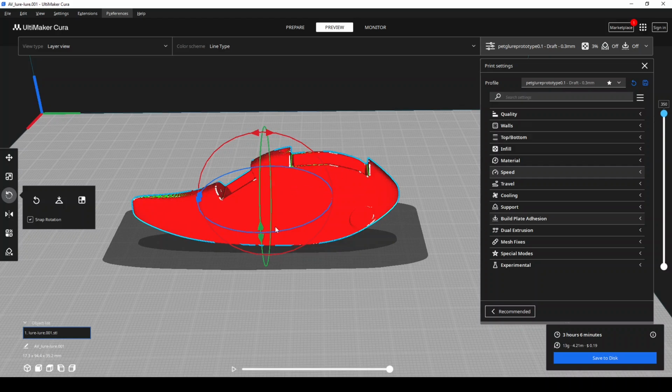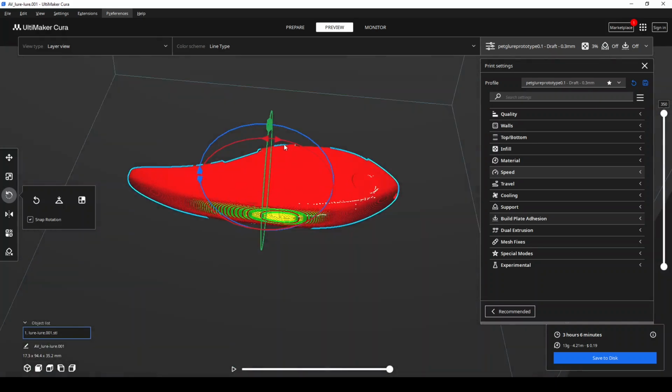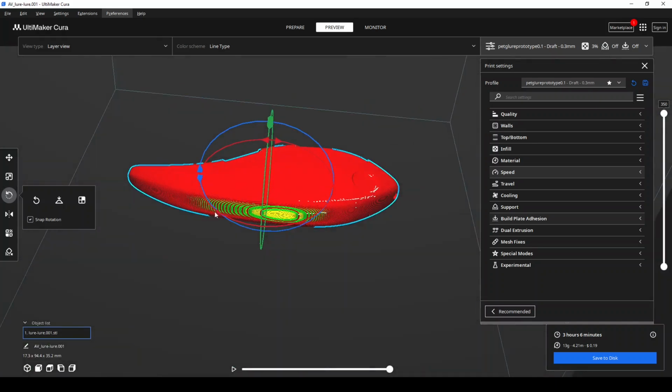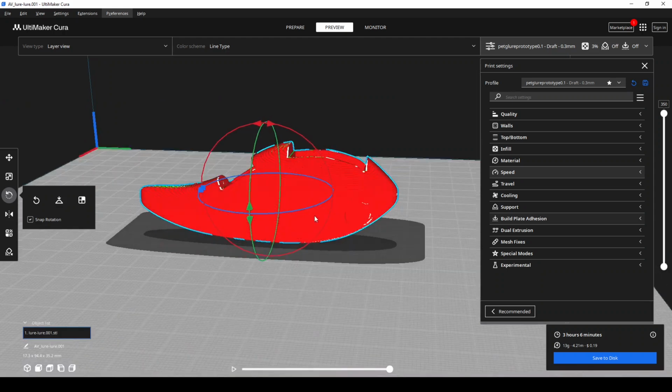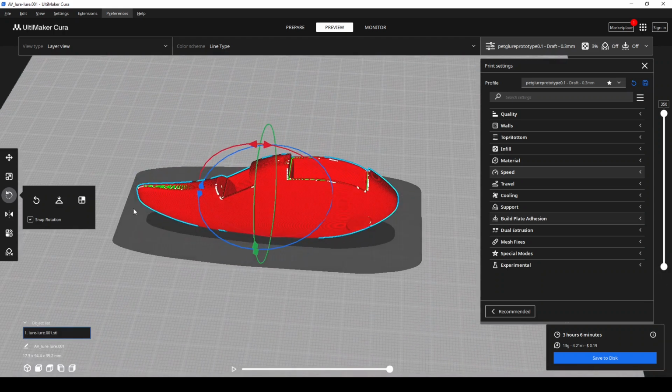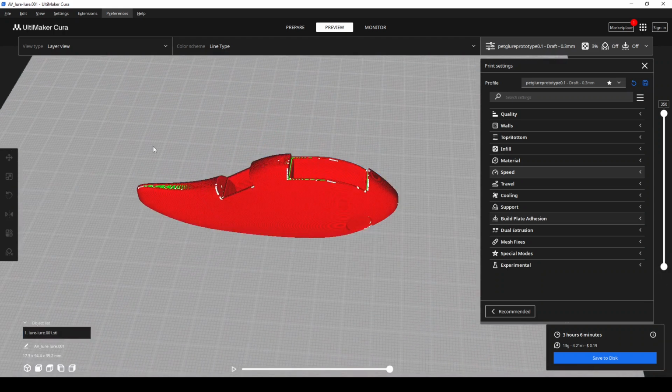I don't have to clean supports off. The areas that will be supported are all along this whole surface, whole as in solid surface, and then I just cut it off with a knife or pull it off with pliers, and then do some sanding, which I would do anyway. So it saves a little bit of trouble there.